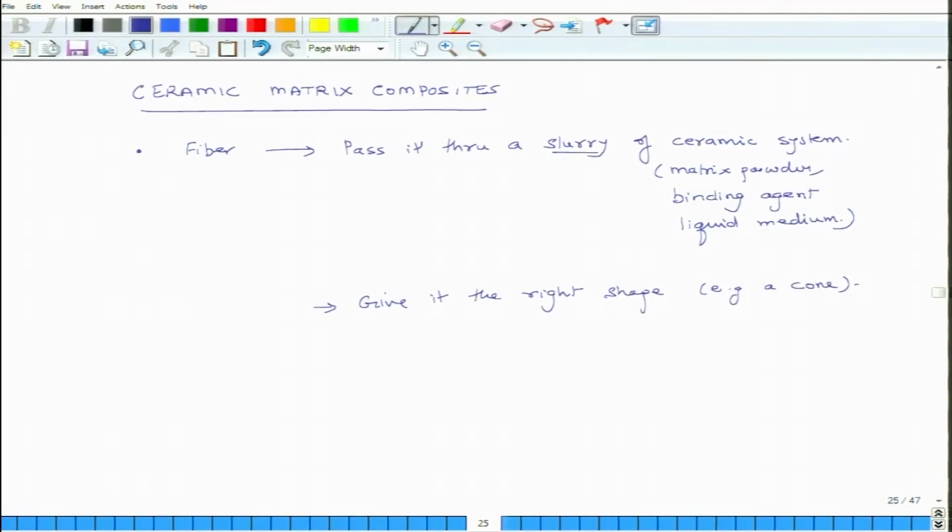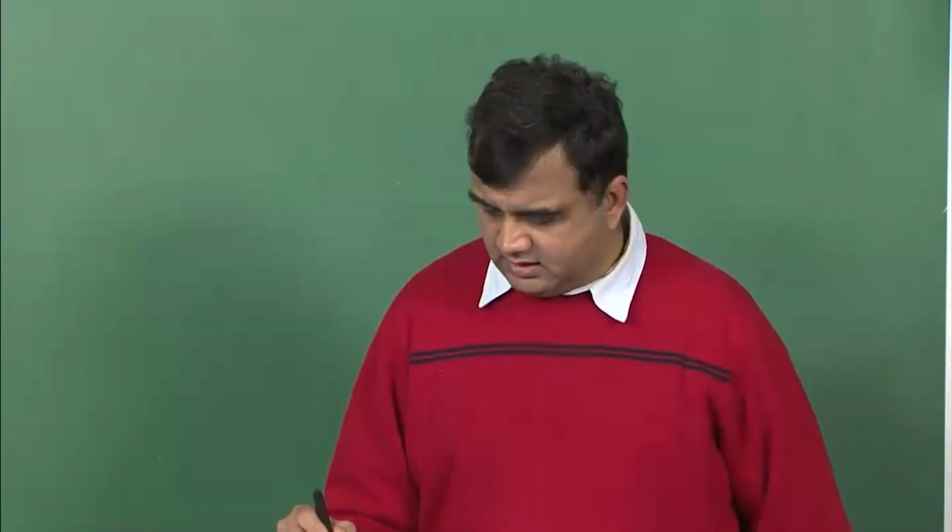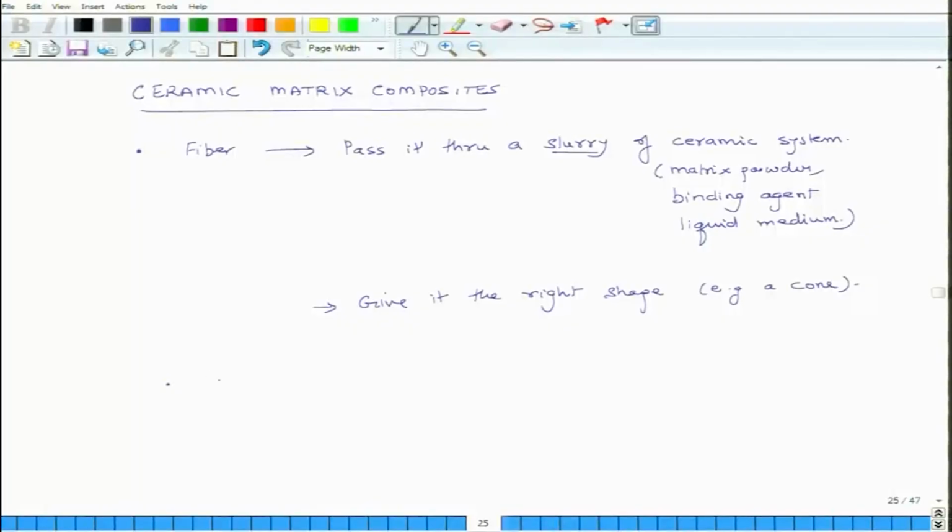This thing can still deform because it is not compact yet, and then you heat it in some sort of inert atmosphere, maybe 1200 C or even higher temperatures.